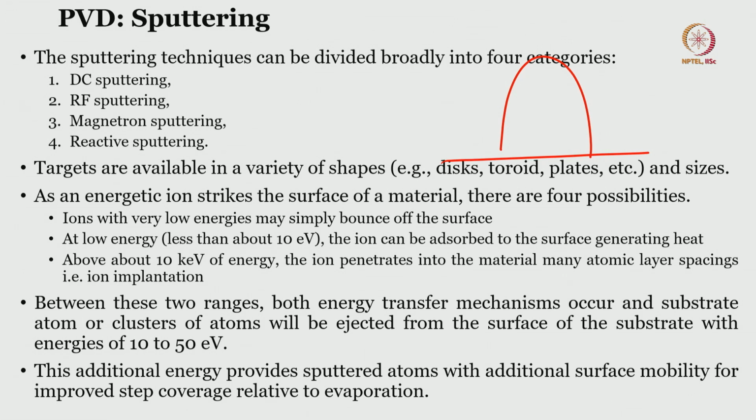that is ion implantation. We will talk very quickly about implantation techniques, and how we can dope silicon with N type or P type. Intrinsic silicon, by doping, we can make extrinsic. But if you want to create a PN junction, let us say, then how you can create this PN junction within an intrinsic silicon or even an extrinsic silicon, we will see. It is called diffusion and ion implantation techniques.